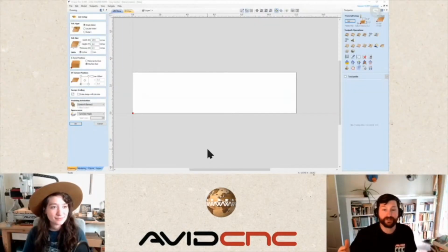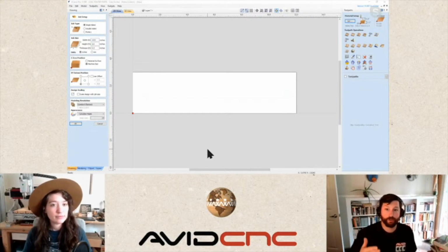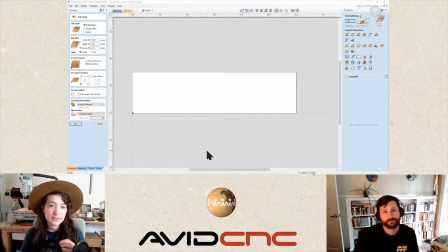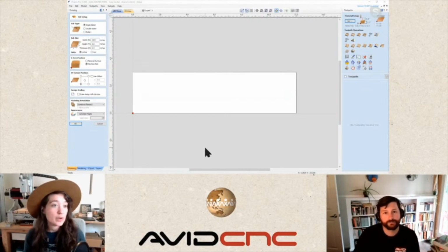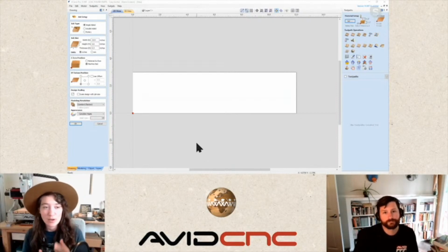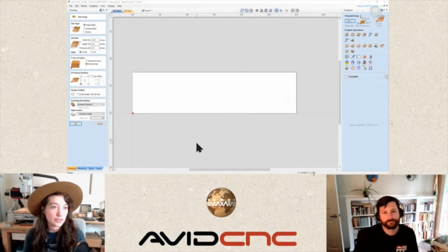All right, let's jump into some toolpaths. Now, these toolpaths can be used with both aluminum and brass, and really all non-ferrous metals, right, Sami? Right, these high density materials like non-ferrous metals with brass or aluminum or zinc, there's several different ones that are going to have very similar qualities. So these toolpaths are going to be very similar. The trick is to do some tests and then make those adjustments. But this is a good starting point no matter which of those materials you have.